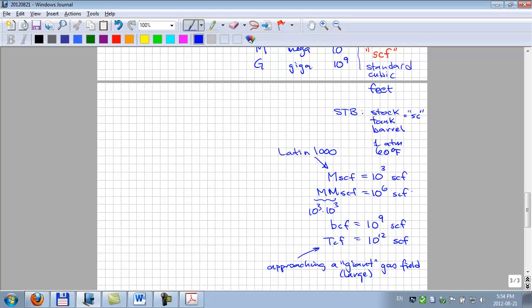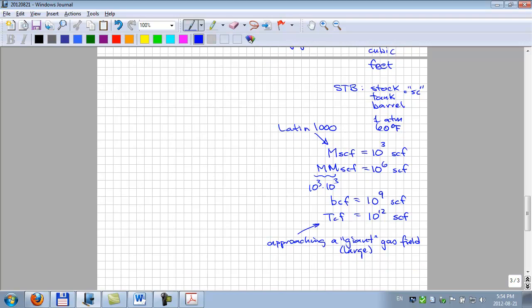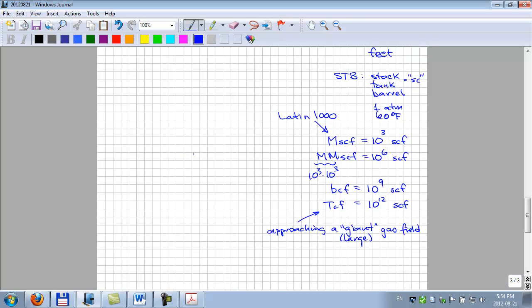So these are volumes in petroleum engineering. They're special terms or units, and you really have to learn them. For metric, the way it's supposed to be written is standard cubic meter; the SPE writes STD cubic meter. But many people just write a capital S for standard condition, which clearly makes the SI committee shake.